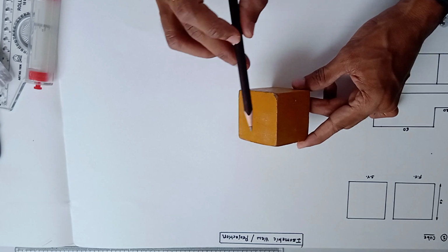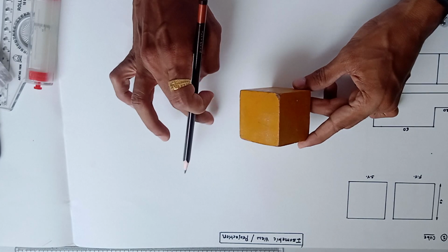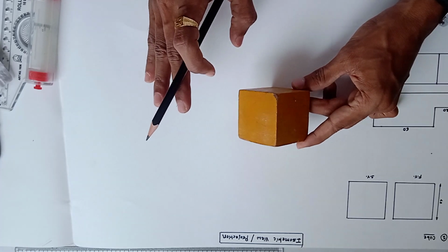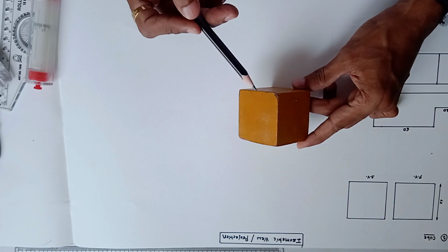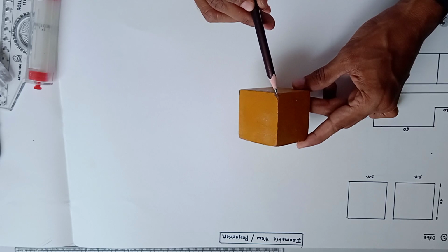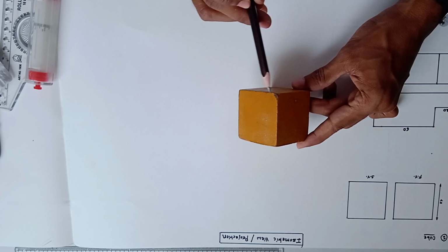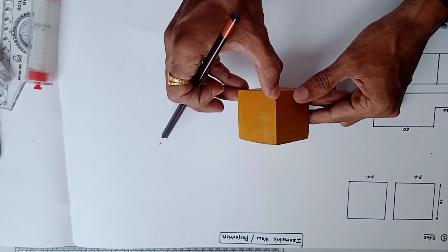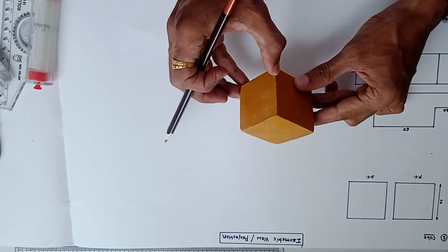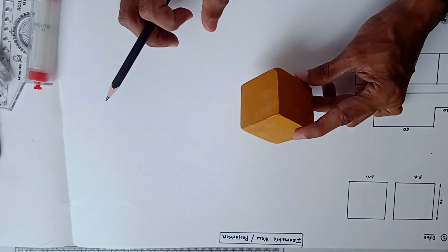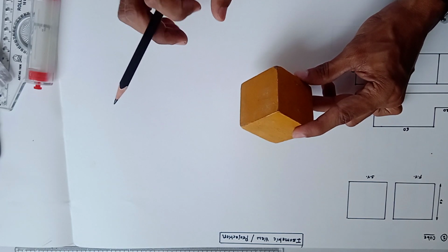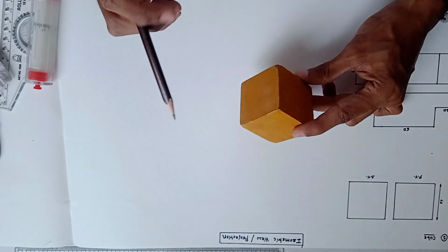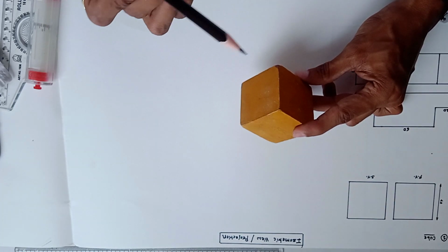But still, if I project this onto the drawing paper, the object will not look three-dimensional. So for this, I will rotate this object again by fixing this corner. This corner will be the origin. If I fix this corner and rotate the object in this direction, right now we can see the three-dimensional view of the object. This view is called the isometric view or the isometric projection. Here the object looks three-dimensional.